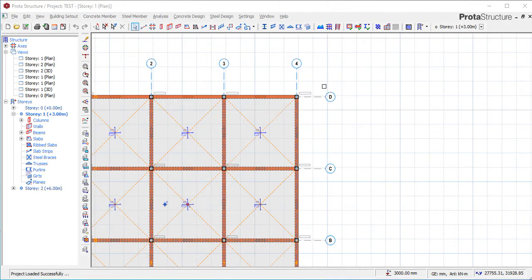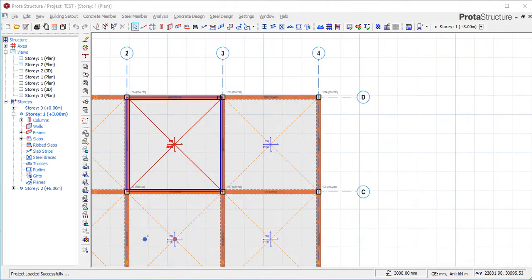I want to show you how to offset. Let's assume our cantilever is at this position. Two ways you can do it: you can either cantilever your slab or cantilever your beam, but I prefer cantilevering my beams because they have deeper depth than the slab. If you cantilever your slab, you just have 150 thickness to hold the bending, but if you cantilever your beam, you have 450 depth.